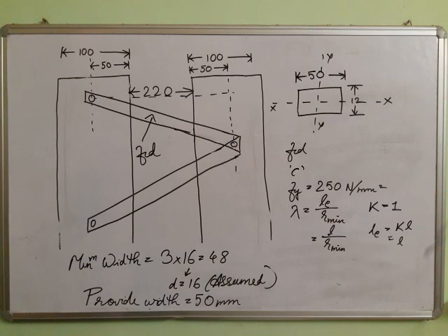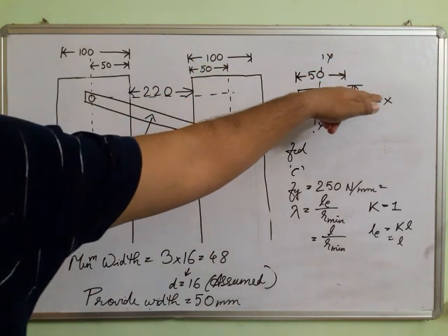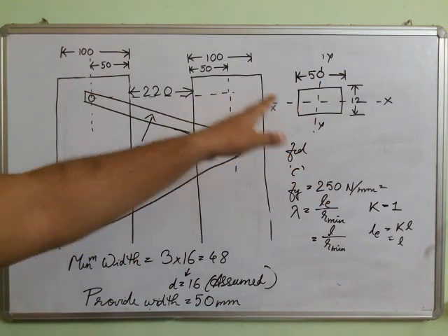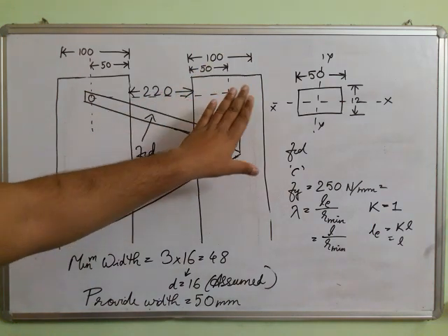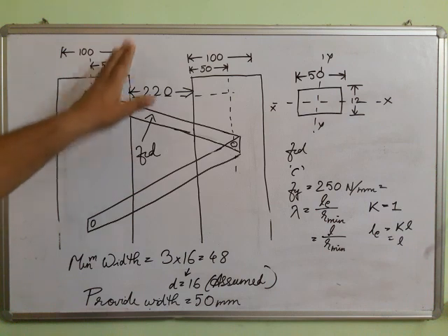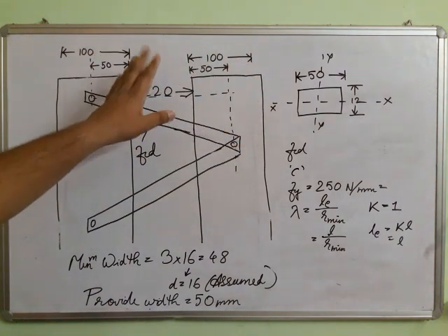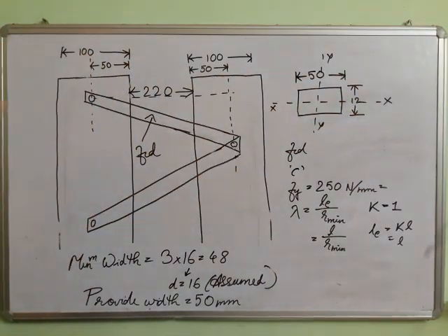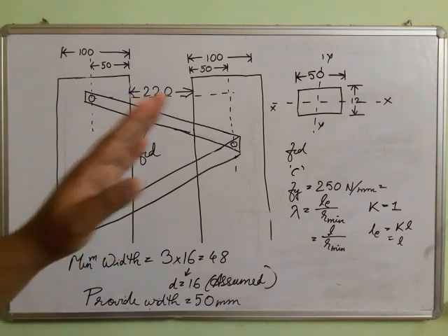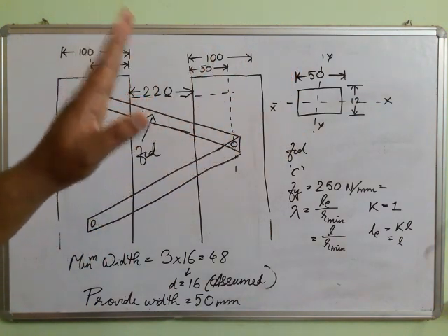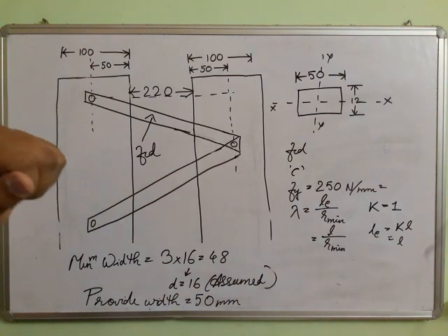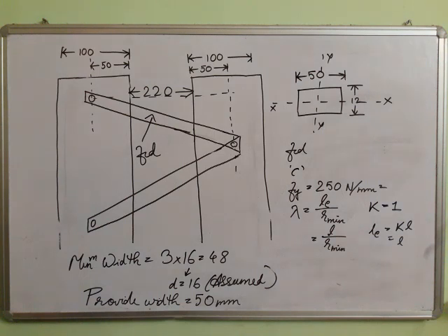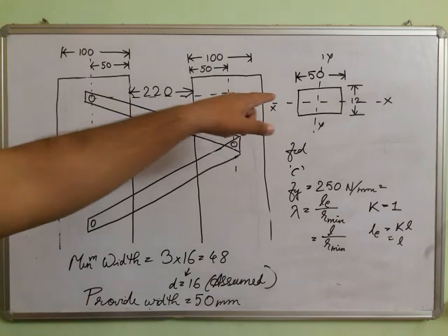So first one is what? Moment of inertia about x-axis and moment of inertia about y-y. These x-axis and y-axis, don't confuse them with the y-axis, x-axis that are there for the channels, or the y-axis, x-axis for the built-up column as a whole. Don't confuse it. This is the exclusive x and y-axis for only the lacings. It is not related with the x and y axis either for the channels or for the built-up column as a whole. So now let us find Ixx for the lacing.